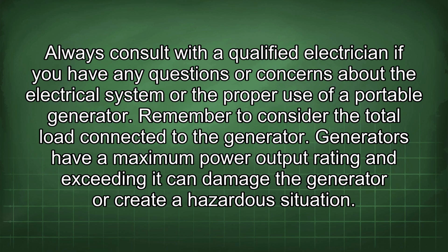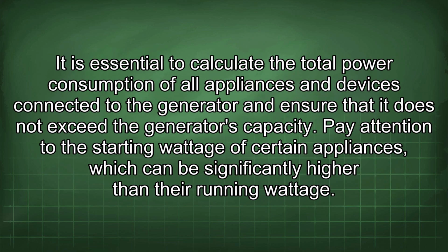Generators have a maximum power output rating, and exceeding it can damage the generator, or create a hazardous situation. It is essential to calculate the total power consumption of all appliances and devices connected to the generator and ensure that it does not exceed the generator's capacity.